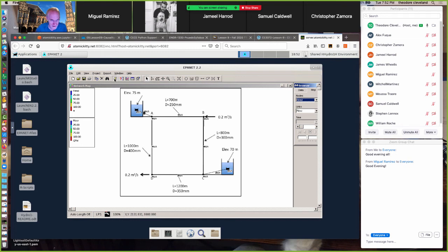We run it. Run was successful. And we now have, I wish I could get it to quit being yellow. You can't see yellow because of the background. But we now have the flow rates in liters per second in individual pipes. We also actually have the flow directions. So coming from node B, water leaves node B through these two pipes, and the sum of these two values should be the 200 liters per second.